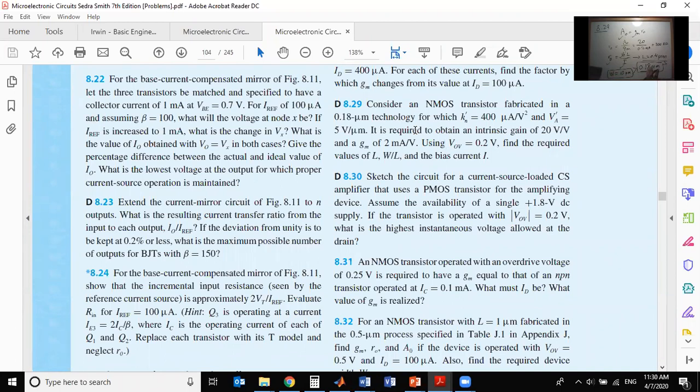He mentioned this just to show you that the factory that fabricates these transistors cannot make anything below 0.18 micrometer. This is the minimum size that this factory can generate. So since your L is 0.4 and your W is 10, then you are safe. This 0.18 micrometer has nothing to do with the solution. It just shows you are on the safe side. But if L or W was less than 0.18, then you have to find another way in your design.